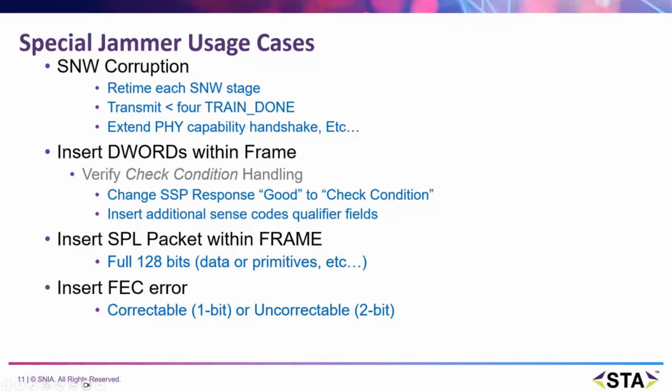Advanced scenarios include speed negotiation, window corruption, PHY handshakes, extensions, and FEC error injection. These tests push devices to their limits and ensure compliance with the SAS 4.0 specification.